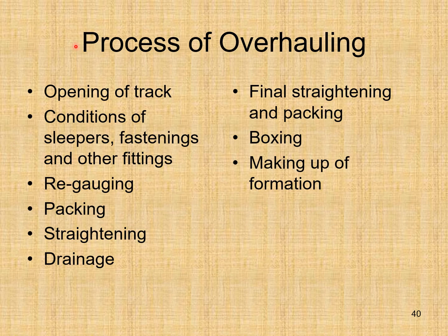Process of overhauling. So different steps you can see: opening of track, conditions of sleepers, fastening and other fittings, regauging, packing, straightening, drainage, final straightening and packing, boxing, making up of formation. So these are the different steps involved in the overhauling.